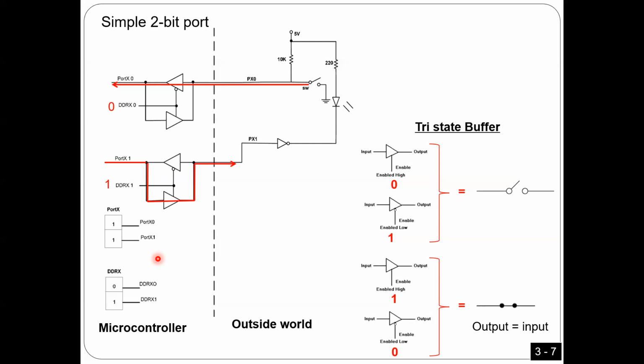So this is one thing. The other thing, how can you do this configuration? Very easy. You have a register. This register is called DDR. So that means we have DDRA for port A, we have DDRB for port B, and so on. Is that okay? So for every port, we have a register. We call it DDRA, B, and so on, to configure this port.